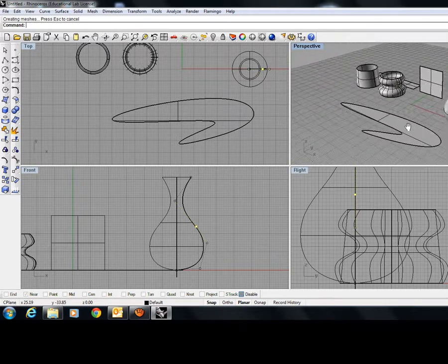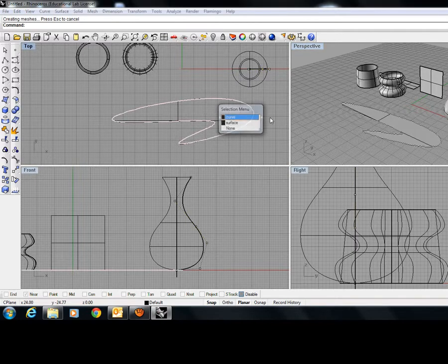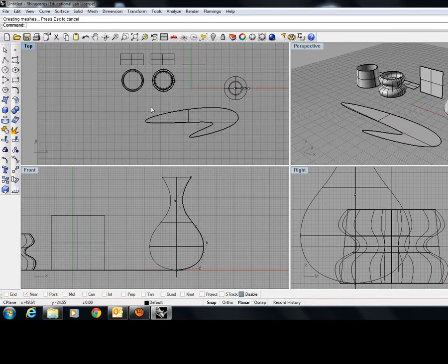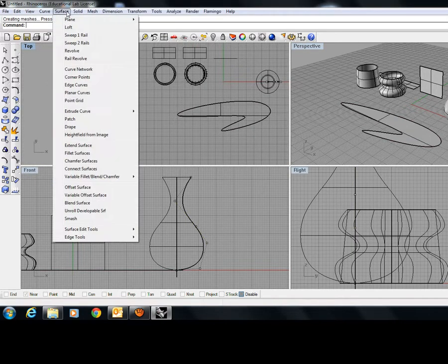curve that I did. Sometimes when you have holes and they're not rectangular or they're not square, then you draw the curve around the hole and then create a surface, and you can attach it to the surface later on. Okay, so that is another way of creating surfaces.